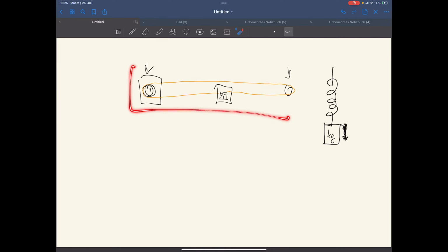Now this is a perfect printer axis. Now what will cause resonances all the time, so we always have one, is the belt itself, and we can assume the belt being a spring for the most part, which means when we expand it by a millimeter due to force, it will have a force x to the center, and if we expand it by 2 millimeters, it will be 2 times this force.